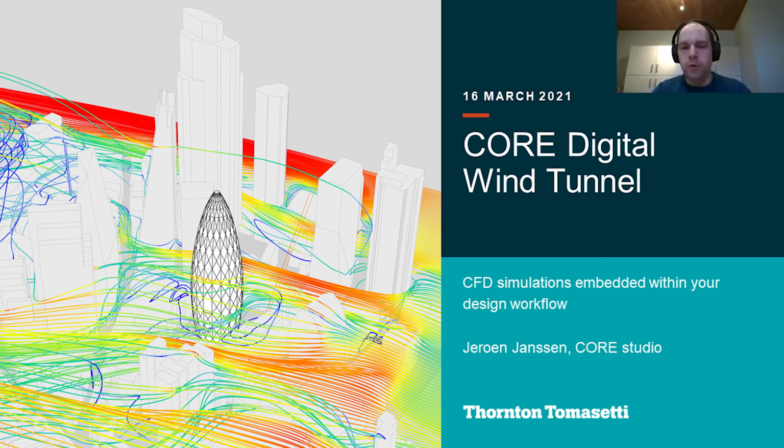That's the common approach for, I would say, 90–95% of the buildings. We can do that in the CFD, and that's what we're doing at this point with these simulations. So the model is rigid. We measure the pressures either on the facade for facade pressures or on the base of the building, and extrapolate that up and find the frequencies like that.